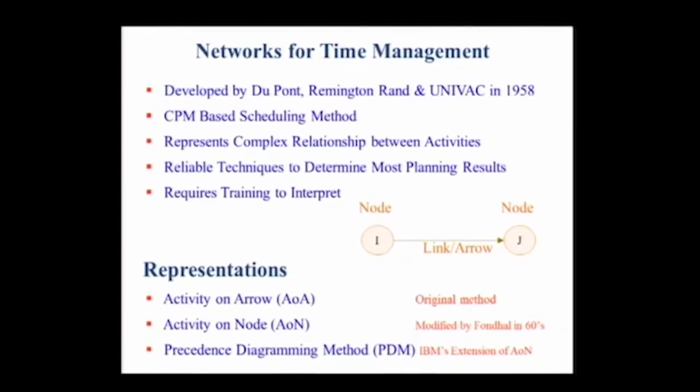One of the real limitations of the network is that it requires training to interpret. You could see something like a bar chart, we can discuss it for half an hour or even less and someone can use it straight away. But when it comes to CPM, you really need quite a few hours of introduction, and even then a lot of practice to be able to use it effectively on a project.